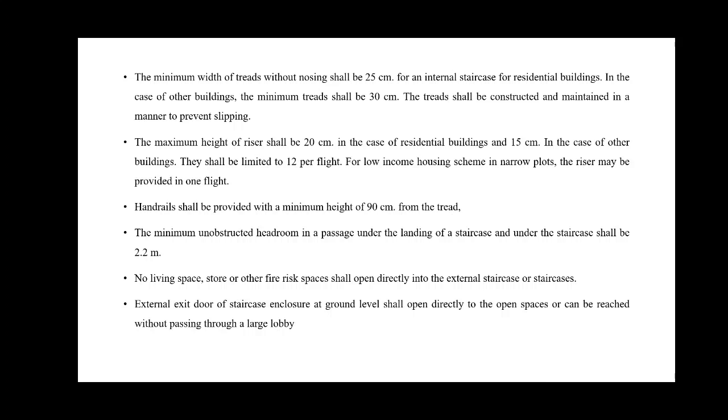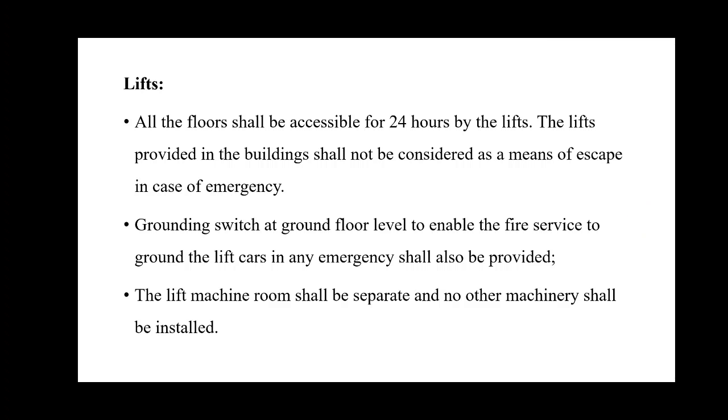The minimum unobstructed headroom in a passage under the landing of a staircase and under the staircase shall be 2.2 meters. No living space, store or other fire space shall open directly into the external staircase or staircases. External exit door or staircase enclosure at ground level shall open directly to the open spaces or can be reached without passing through a large lobby.